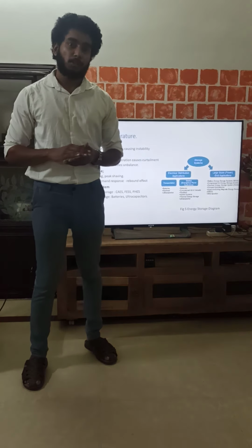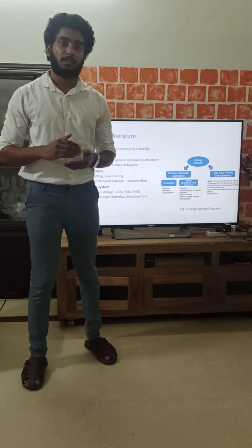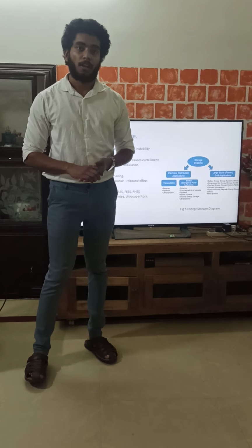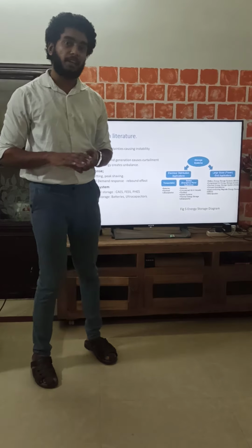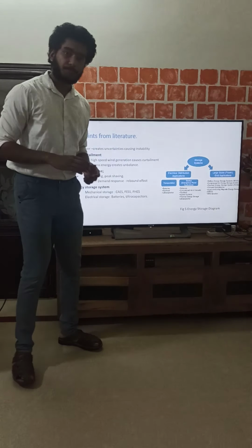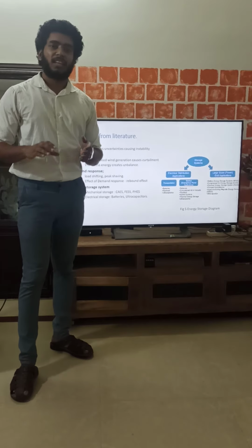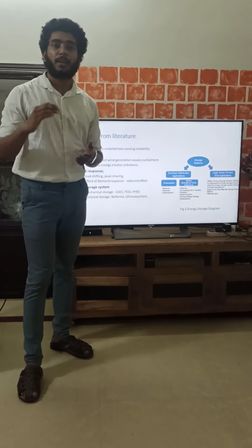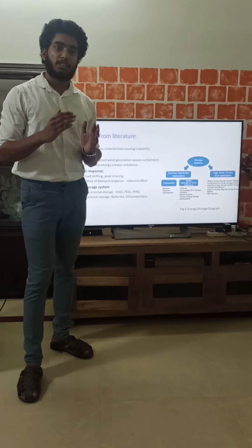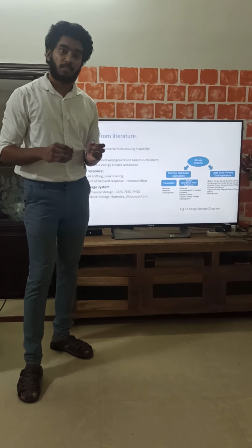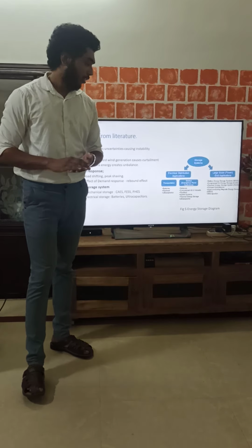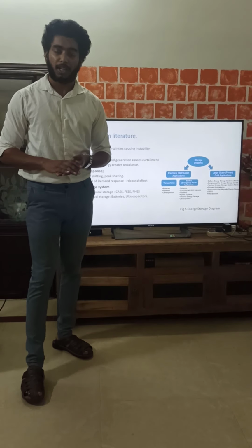Studies show that adding flexibilities into the system reduces the curtailment. One such flexibility is demand response. So what is demand response? Demand response is a strategy used by utilities to shift or reduce the total demand in a peak time to another period of time.